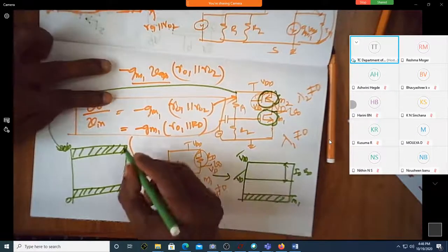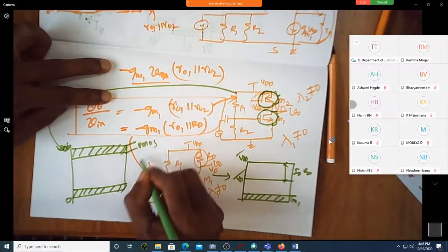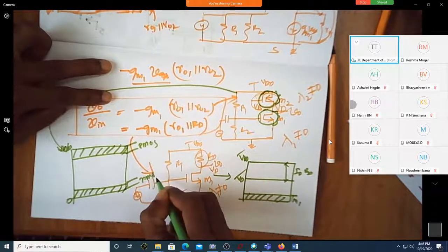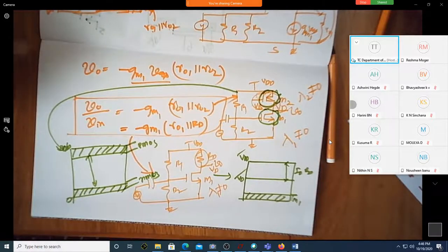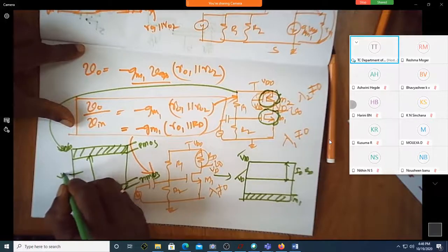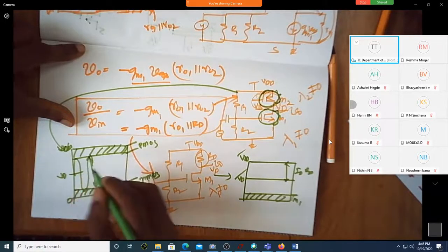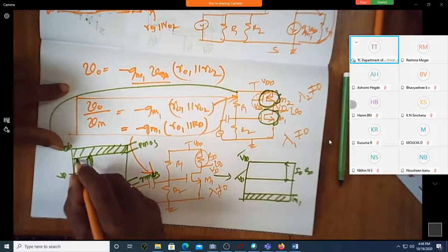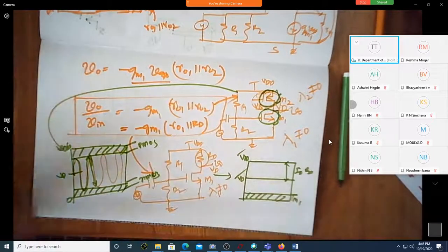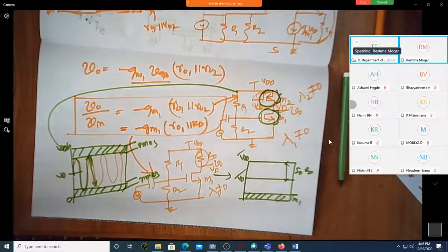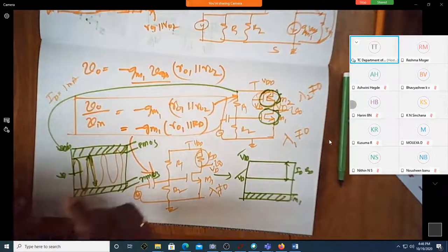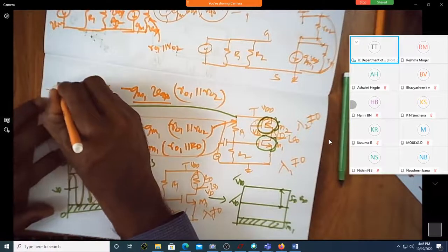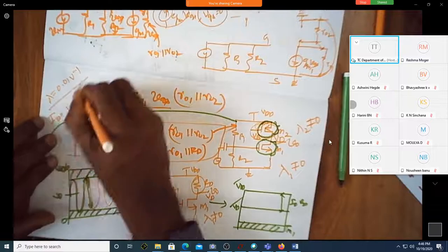See, this is dedicated for PMOS. This is dedicated for NMOS. You have this much swing available. Now you keep your VD at the midpoint and then keep swinging. Correct? Now let us take an example of ID equal to something like 1 milliampere. Let us take an example. Correct? And lambda is equal to 0.01 volt inverse.